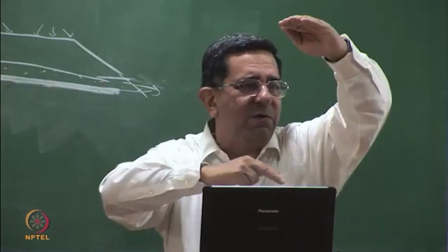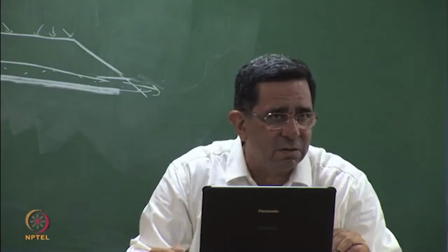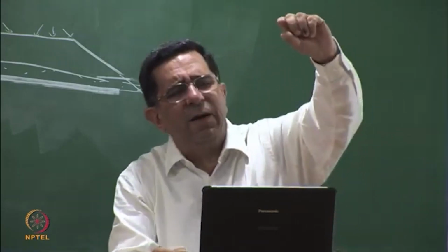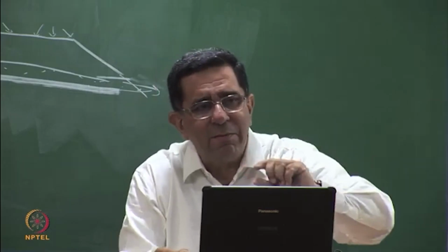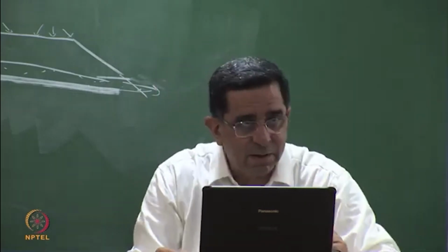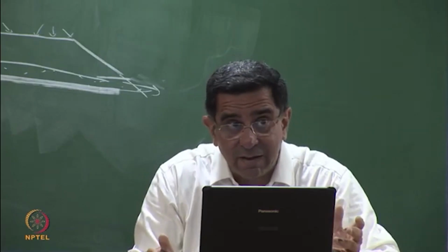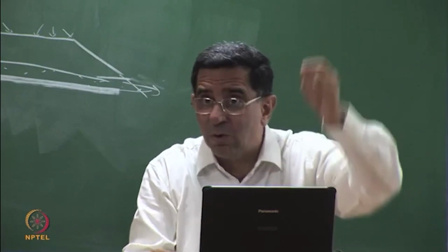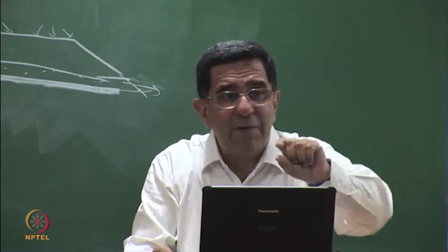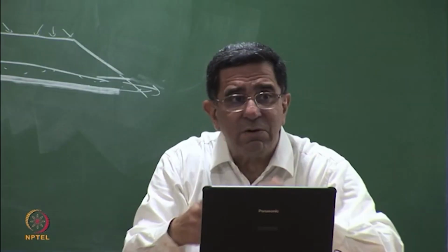So you say, okay, I've got a 15-meter deep contaminated zone. So they say, okay, we will inject it at every 1 meter or 4 meter depth. You have to tell him it's clay. I can't even inject water into clay. You can make a borehole. I can go and place this bioculture at that level, but how is it going to travel?